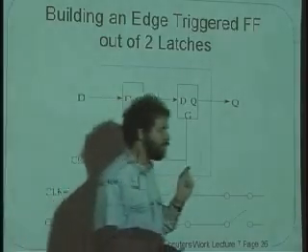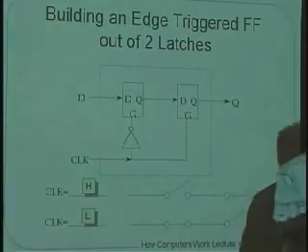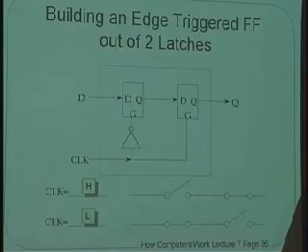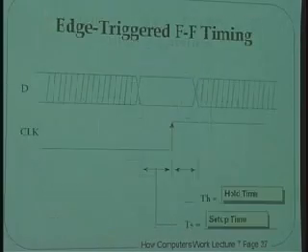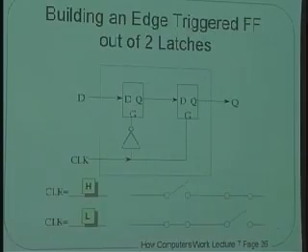And it takes a snapshot at an instant because there are two latches in series with each other, controlled in opposite phase. All right. And somewhere you put the enable in there so that you could, yes.